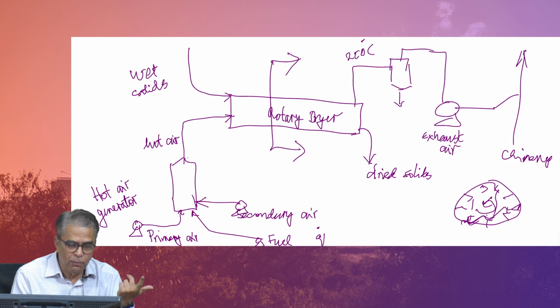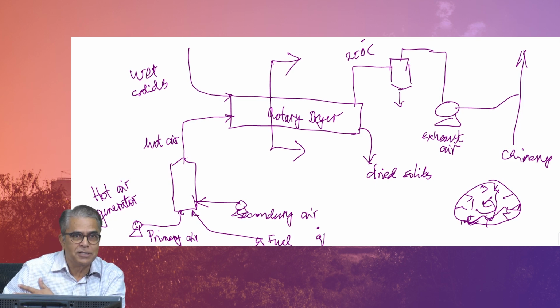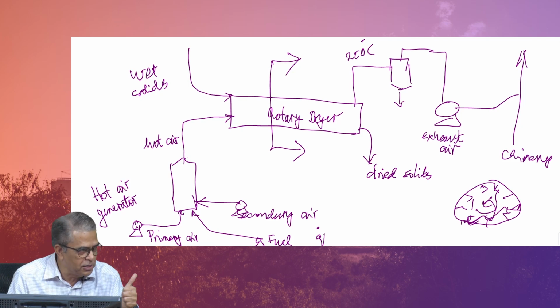At a minimum, the idea is to burn the fuel, right. So at least you must know the minimum quantity of air required, by stoichiometry, very clearly. The key assumption that we will make is air has 20% oxygen, 80% nitrogen by weight, or 21/79 if you like. If you want to be very accurate, you do a nitrogen analysis at the site, find 18.7 or whatever. So, you will make one assumption.